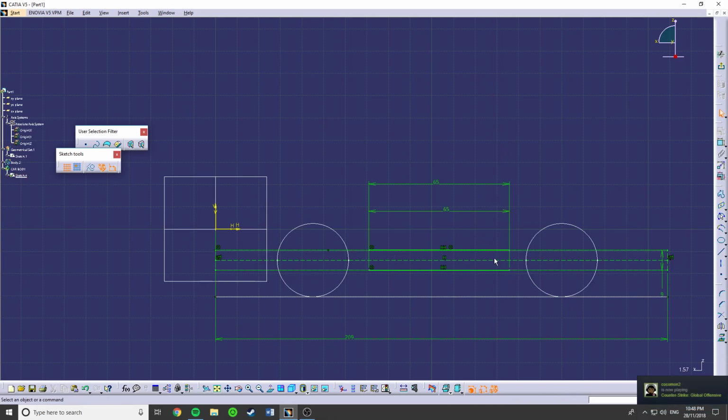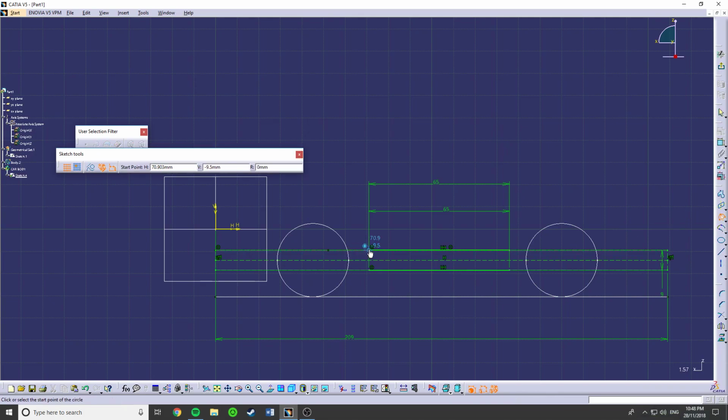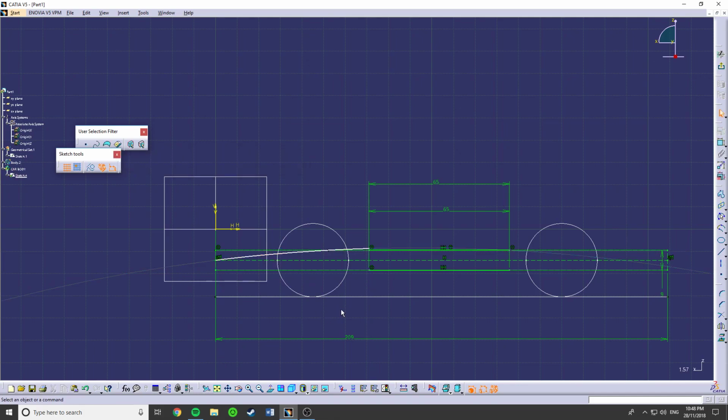Now we don't want just a flat body and then a flat end. So what we want to do is actually curve the body into a kind of pointish thing. So we're going to use this tool called the 3-point arc with limits. We click on the 2 points we want them to join into. In this case, we're going to go this point here and the end point here. And then we can choose the kind of arc we want to follow. So say I want it to curve into a kind of thing. We can go there. But obviously this isn't constrained.